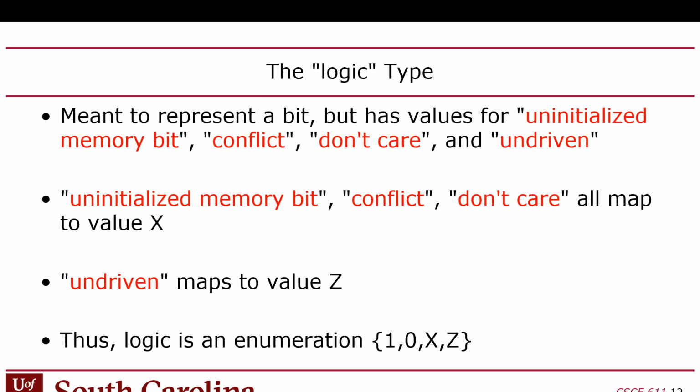In general, you should only have one logic circuit's output connected to each wire in your design. There are some exceptions: tri-state buffers, where you can electronically disengage a module's output from a wire. So there are cases for that.